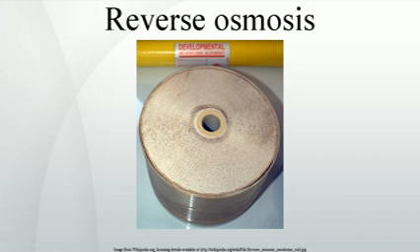Dosing. Oxidizing biocides, such as chlorine, are added to kill bacteria, followed by bisulfite dosing to deactivate the chlorine, which can destroy a thin film composite membrane. There are also biofouling inhibitors, which do not kill bacteria, but simply prevent them from growing slime on the membrane surface and plant walls.